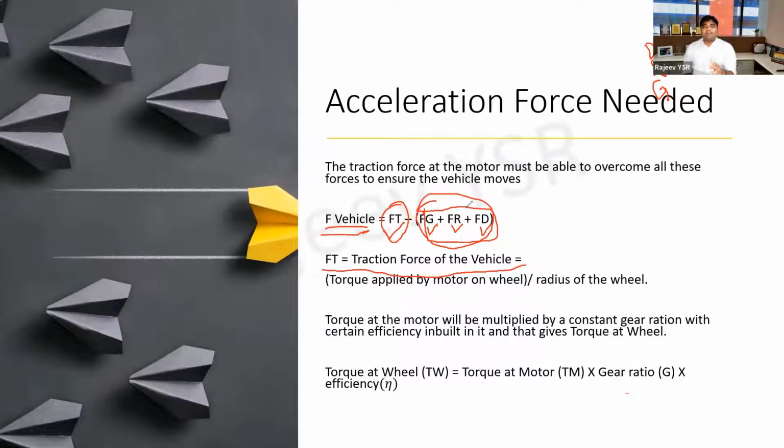This is how you calculate, right? Suppose you're building a four-wheeler, a three-wheeler, or a two-wheeler, those fundamentals I've already given. What would be the coefficient of drag? What would be the coefficient of friction? What would be the rough frontal area? This is how you arrive at the force that is required, and from there you calculate the torque required. Now, for any motor that you buy, there is one specific curve that you need to see. Any understanding what that particular curve is? The curve is the torque versus power curve, which we are going to talk about.